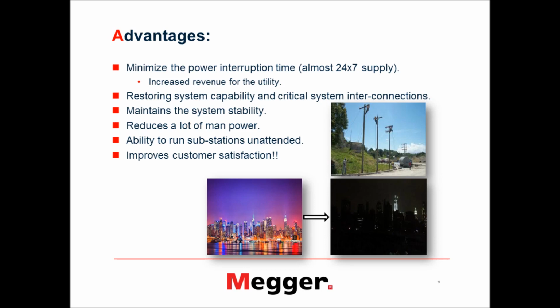Not just that, when you have a reclosure in your system, especially in a transmission line, you're restoring the system capability and also the critical system interconnections. Sometimes there is a tie, and whenever there is a fault happening in the tie system, you might want to restore the power flow as soon as possible, so that a huge area on the other side does not get affected.